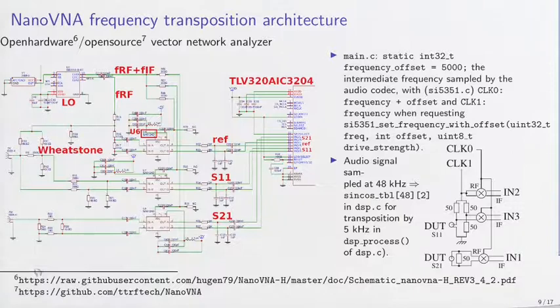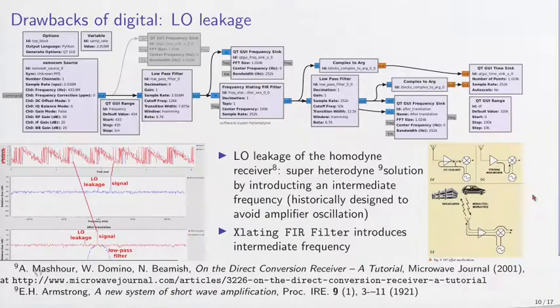So this two-step frequency transposition helped us solve the IQ imbalance issue, the amplitude and phase difference between I and Q and the slight phase offset that might remain. This intermediate frequency will also allow us to solve close-to-DC local oscillator leakage issues that might plague measurements of low frequency spectral components of the received radio frequency signal.